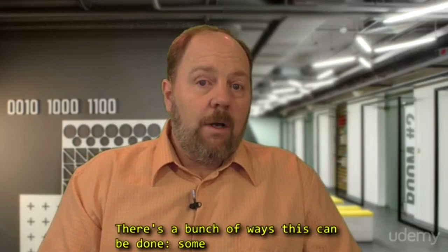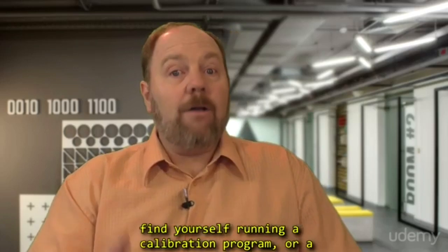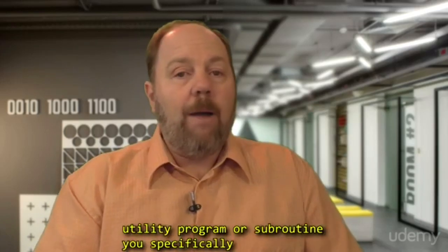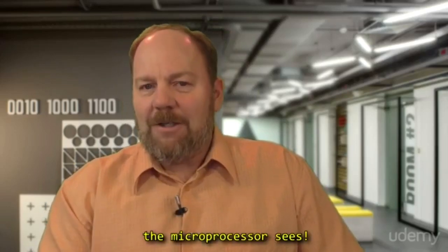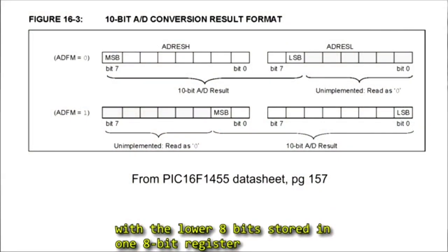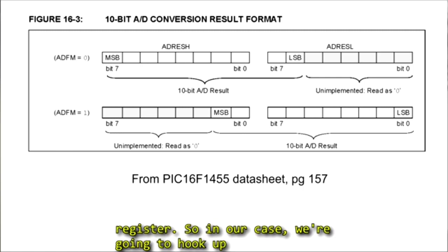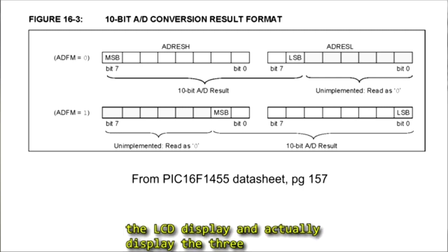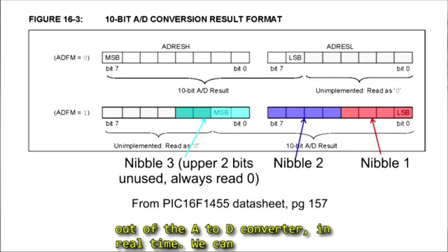Now, there's a bunch of ways you can do this, some simple, some more complex, but from now on, you'll find yourself running a calibration program or a utility program or subroutine that you specifically wrote just to tell you what the microprocessor sees. The PIC's A to D converter is a 10-bit converter with the lower 8 bits stored in one 8-bit register and the upper 2 bits stored in another 8-bit register. So in our case, we're going to hook up the LCD display and actually display the three nibbles as 3 hexadecimal numbers coming straight out of the A to D converter in real time.